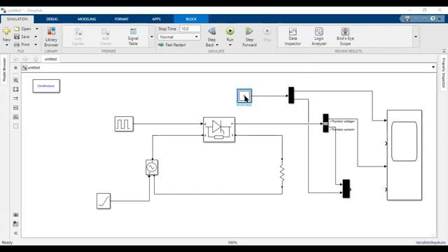So the first will be click on the control voltage source, select, and the second one will be series RLC branch current, the current through the load branch. Click on this. Selected measurements. So the first terminal is the control voltage source, the second terminal is the load current.